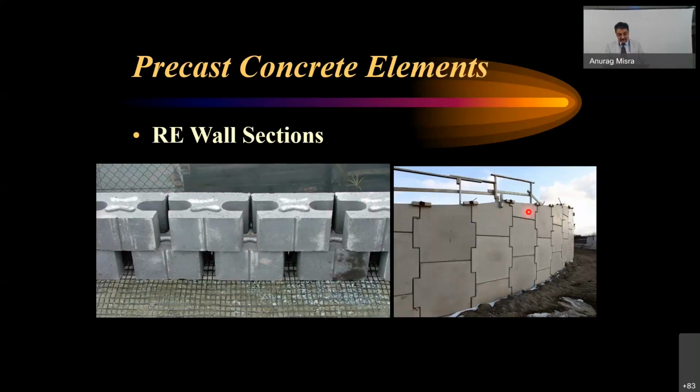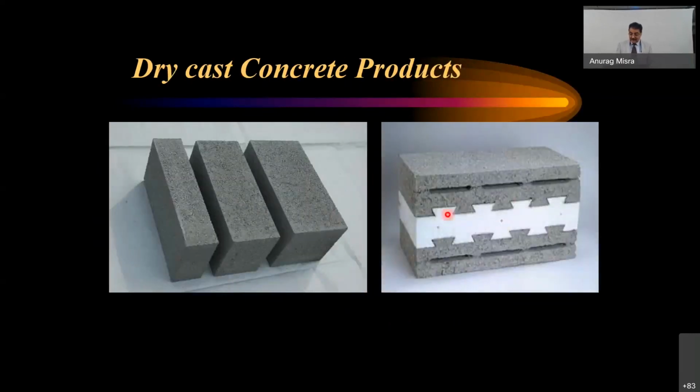Rather than using these wall sections, these days these are becoming popular and quite effective as well. This is an insulated masonry block, so it completely avoids the requirement of the double wall and saves quite a lot of construction area, because otherwise you lose about 20% of the total area in double wall construction.